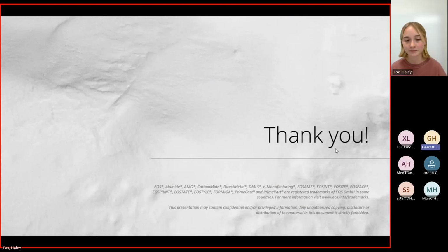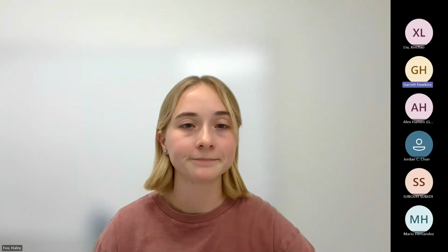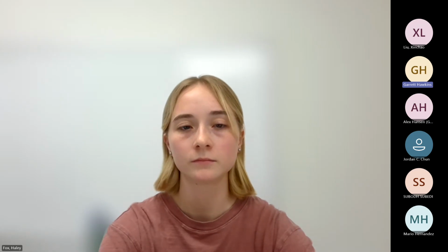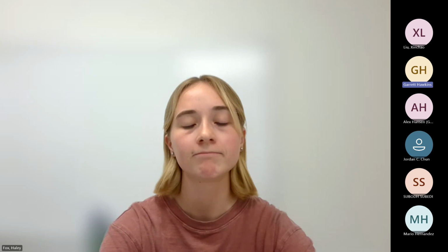I had two thoughts, Haley, and a question. Sure. So the one thought I will add is Haley talked a lot about post-processing of parts after you get it off. And that is one of the largest cost additions of additive parts. And so when we talk about DFAM and when we talk about these drone chassis and stuff, we want to see you take into consideration not just can it be printed, but can it be printed so that it doesn't need as much post-processing?